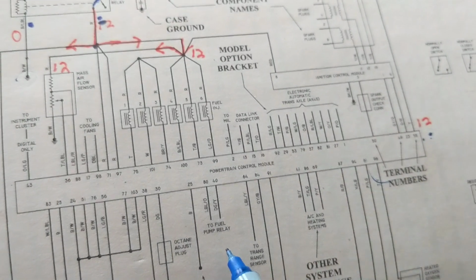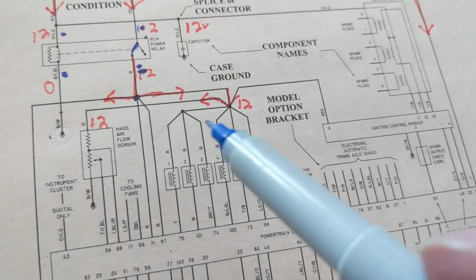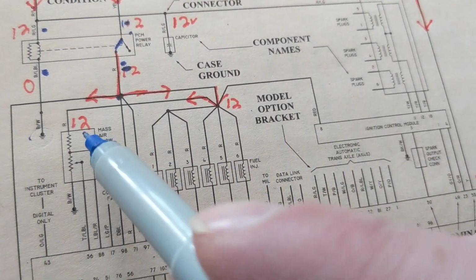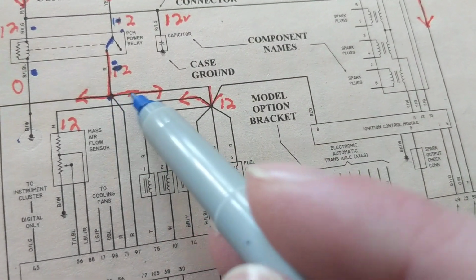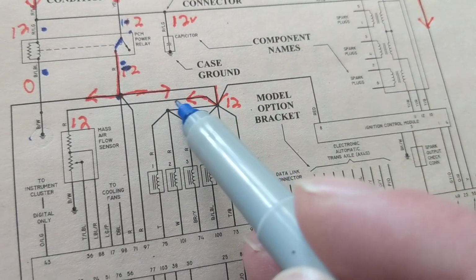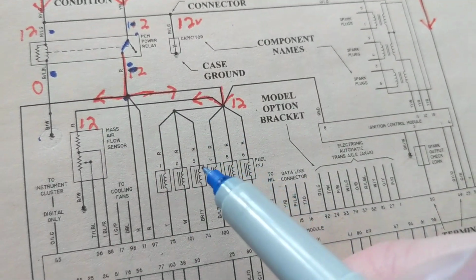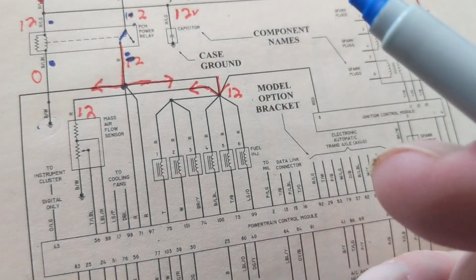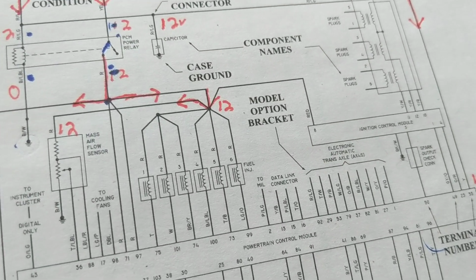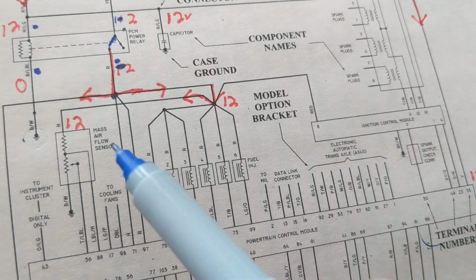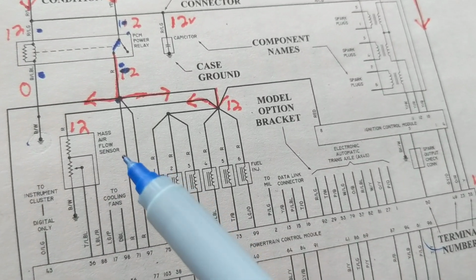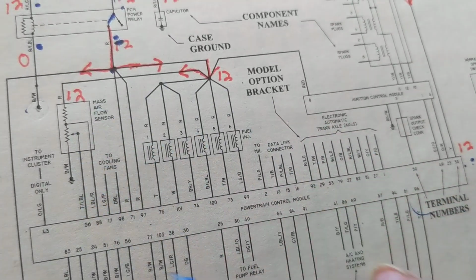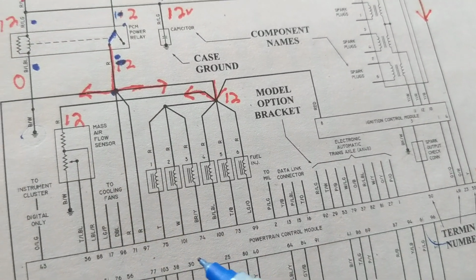Okay? Very important. Mass airflow sensor. What gives you the 12 volts for the mass airflow sensor? Right here. This is the connection. A splice. We come over here. Follow the arrow. We come over, 12 volts. Now, mass airflow sensor. When it comes, there's always a question: do you get aftermarket? Do you go to the dealer? What do you do? When it comes to air-fuel ratio determined by the computer, you see this is an input to the computer.